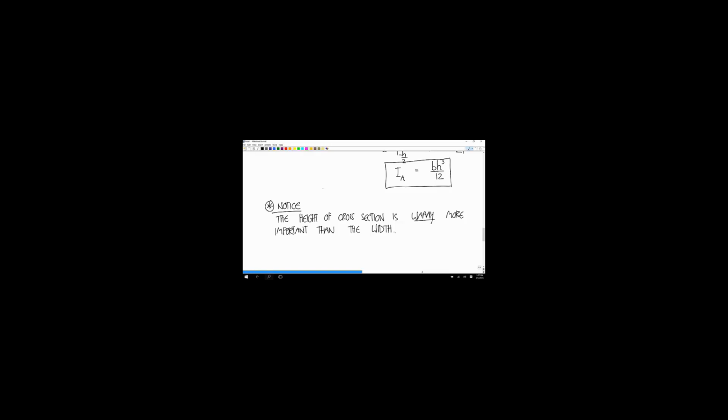It should have a very low area moment of inertia. So look at this formula, and you know what happens when you plug these in this configuration. The base is big, but the height, the thing that you cube, is tiny. And if you cube something tiny, it gets super micro tiny, okay? And so that's why this has no ability to support bending loads like that.